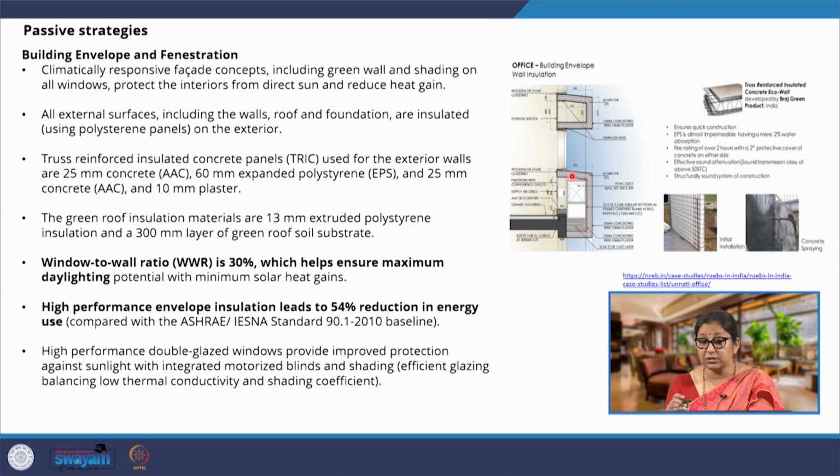And what is happening? The HVAC ducts are running through this cavity that has been created. So, this cavity protects the indoor spaces from receiving a lot of heat. This window gets a projection which is continuous, it remains shaded for most of the time, it cuts off the direct radiation, but allows the penetration of sufficient daylight, because it is like a continuous window that has been provided.